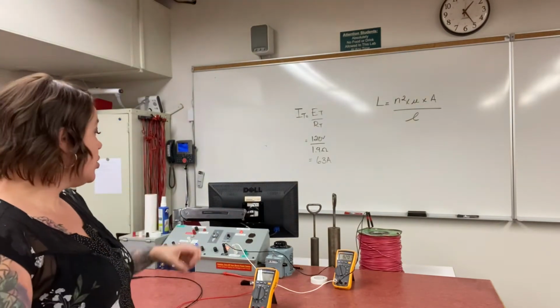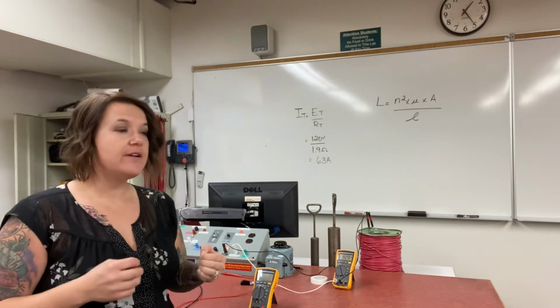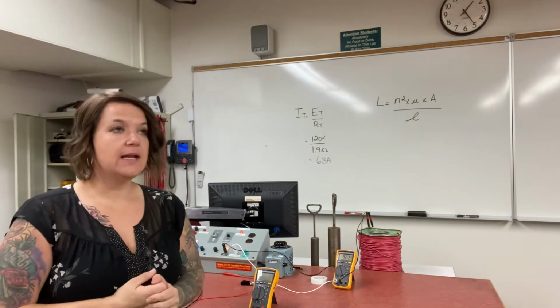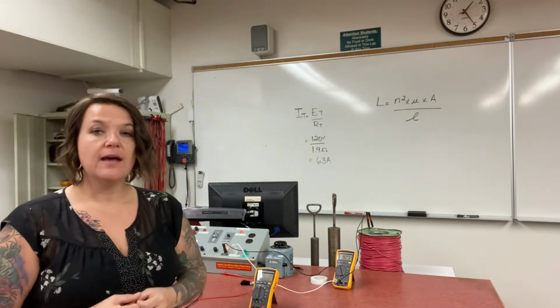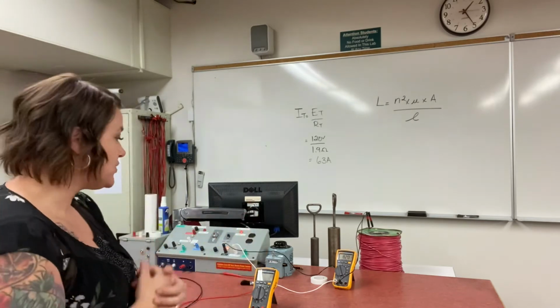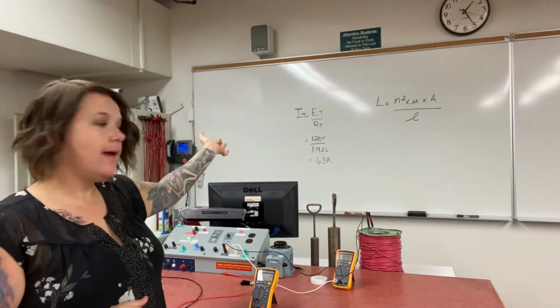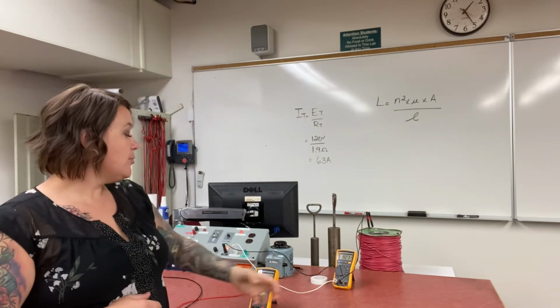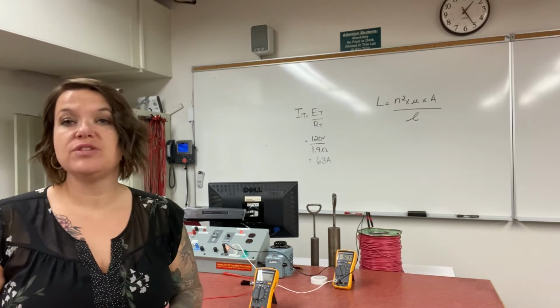Okay, so you can hear the coil actually humming, which is a very typical sound in an electrical place of distribution, right? The sound of humming. A lot of times that's an indicator of a coil generating voltage, right? So our expected current was 63 amps, but you can see here on the multimeter, I'm only reading 8.2 amps.